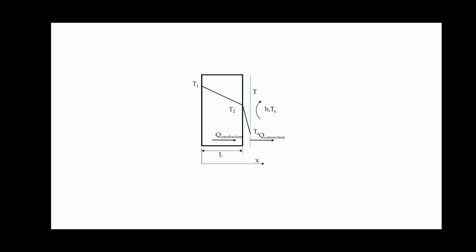This was stated qualitatively. Now, in this lecture, let us provide a parameter based on which we can check the applicability of lumped system analysis. For this, let us consider a steady state heat transfer in a plane wall. I'll consider the thickness of the slab as L. On the right side of the slab, we have a fluid with convective heat transfer coefficient h, and the temperature of the fluid is T∞.